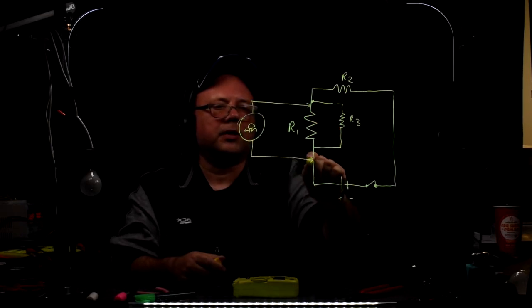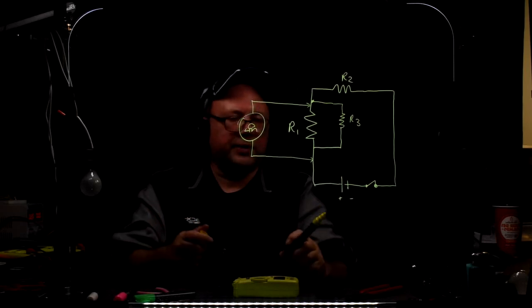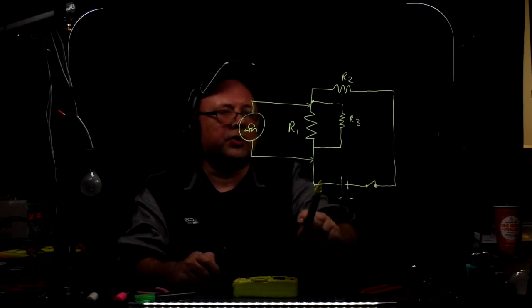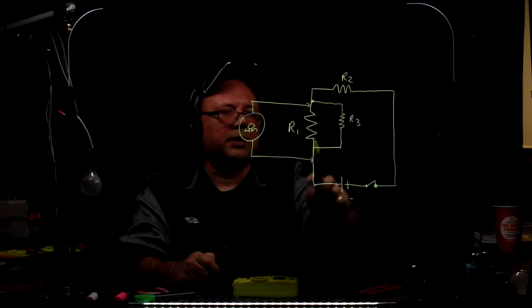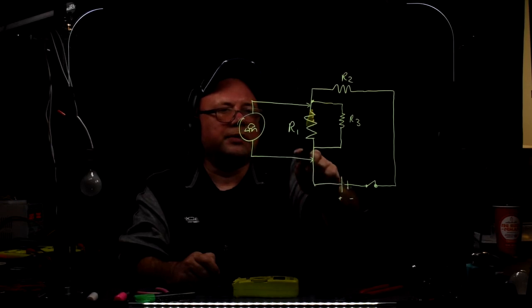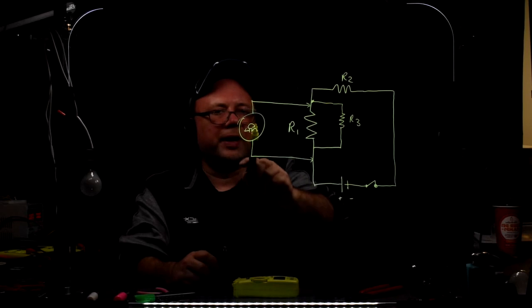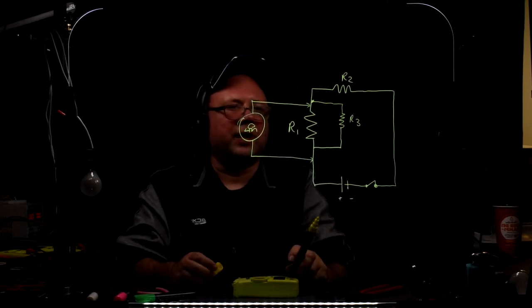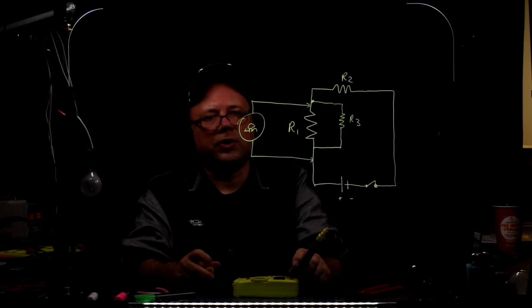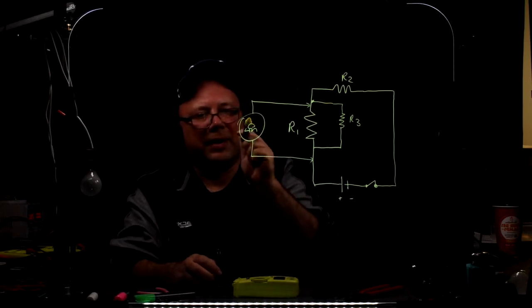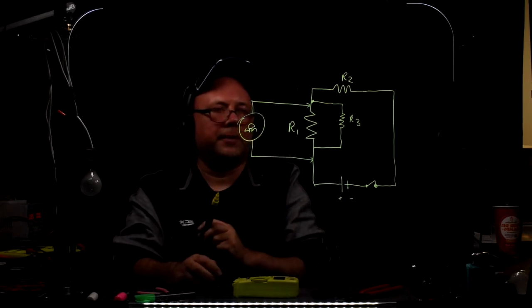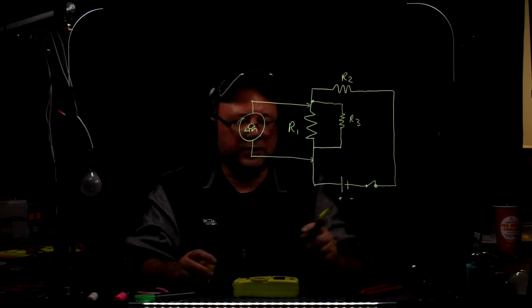Is this correct? It is not correct. First of all, the circuit is not de-energized. Because there is going to be a current flow through this resistor, that means there is going to be a voltage across this resistor when the circuit is energized. This voltage is going to start fighting with this voltage that is introduced by the ohm meter, and we're going to have some conflict of voltages, as a result of which probably you're going to damage this ohm meter here.